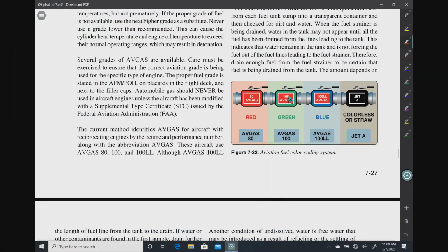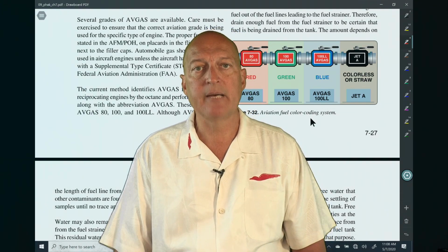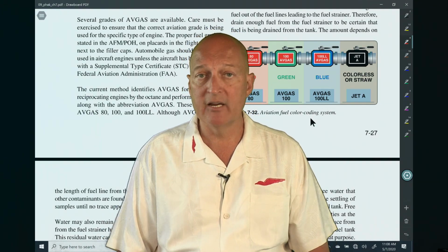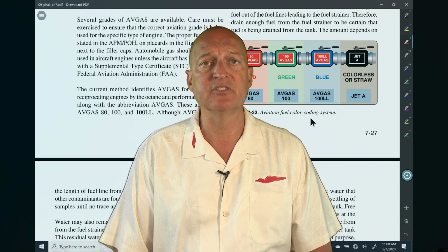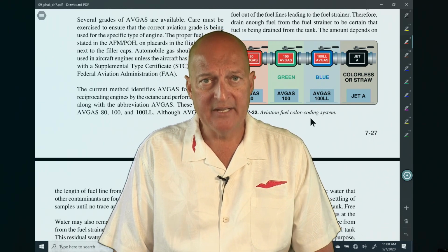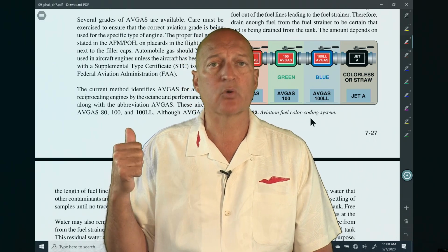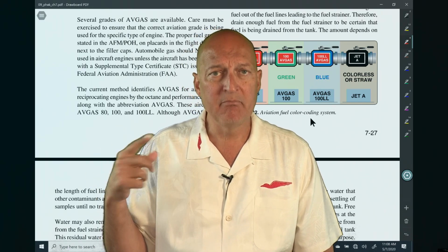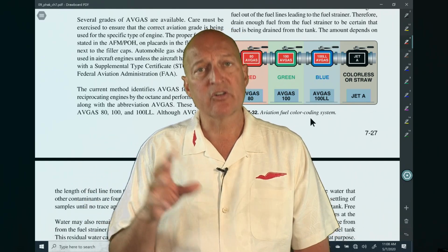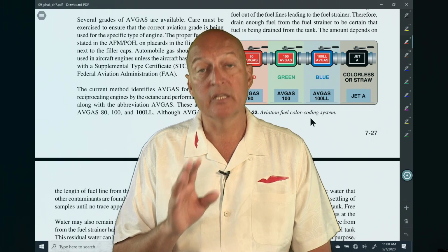There's different kinds of fuel, as you might imagine, although there are not as many as there used to be. Figure 7-23 talks about the various different types of fuels, and back when I started flying airplanes, you did see different types of fuels. Now, everybody is using 100 low lead or Jet A. Jet A is for jet engines or engines that are run by diesel engines. 100 low lead is more akin to gasoline that can be found in your car, a little bit different.